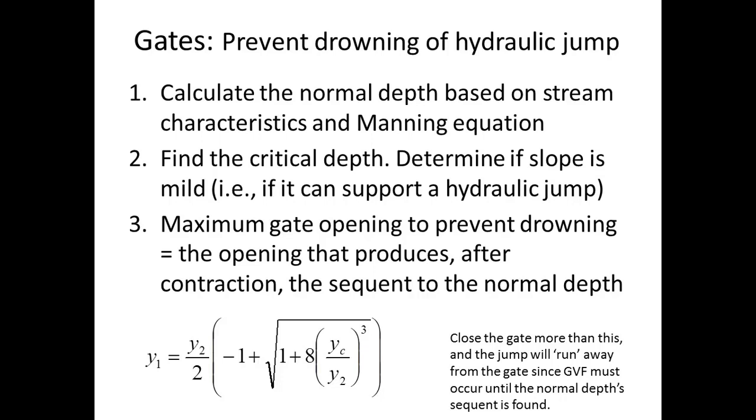And so it's the depth that has the same amount of momentum function. It's the alternate depth that, well, I don't want to say alternate depth, because the alternate depth is the one that has the same amount of specific energy. It's the sequent or the conjugate depth.